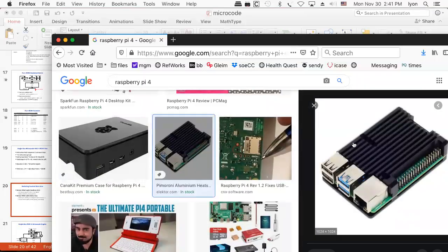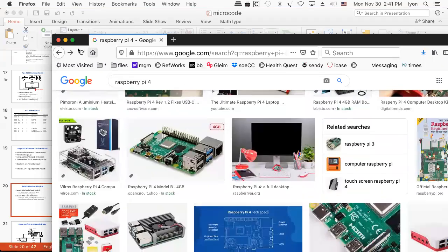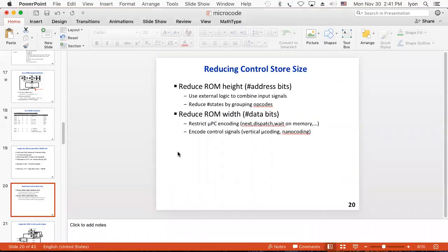This is quite typical. The Pimoroni is a fanless heatsink. It's just a mass of metal, and they stick that on top of the hottest of chips. And then the whole thing is supposed to have a little air circulating naturally around it. If you put this inside of a tight case, I think it's just going to cook it. Aluminum is a very good conductor. So that's the Pi, such as it is.